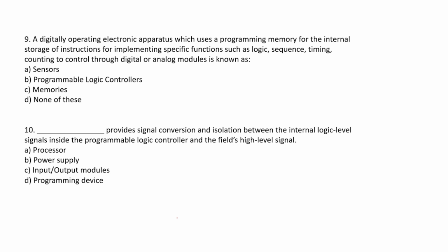For polar, also a partial sphere. For SCARA, a cylindrical work volume. For Cartesian coordinates, a rectangular solid. And for the delta type, a hemisphere is given as the work volume. So those are the joint notations for the five arm and body configurations which are available.